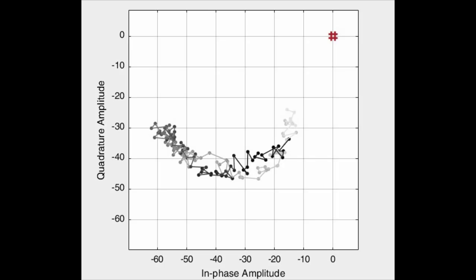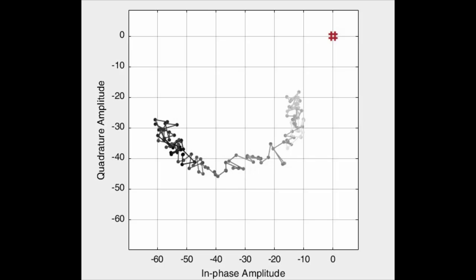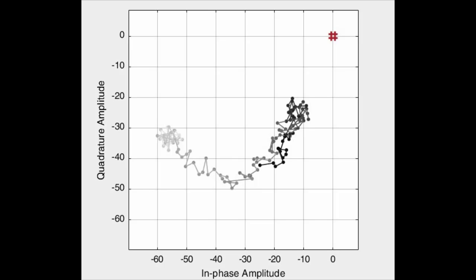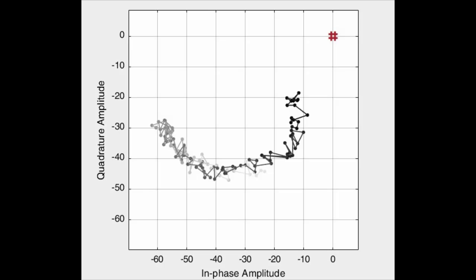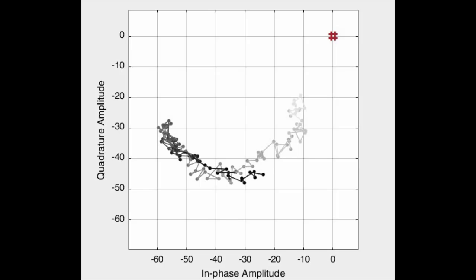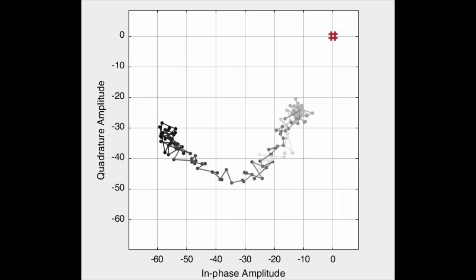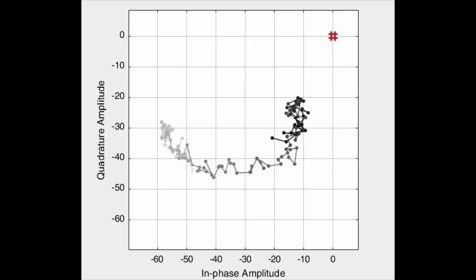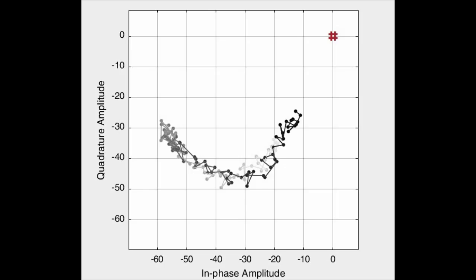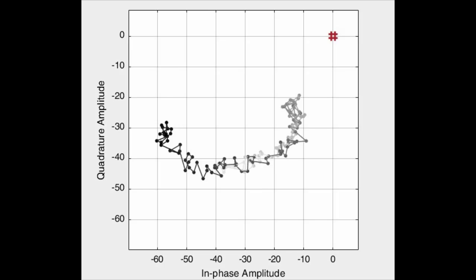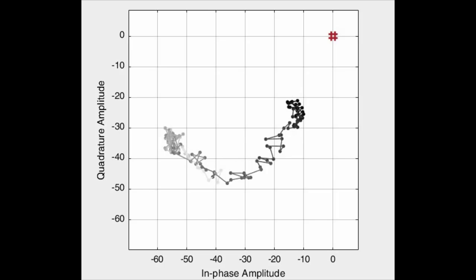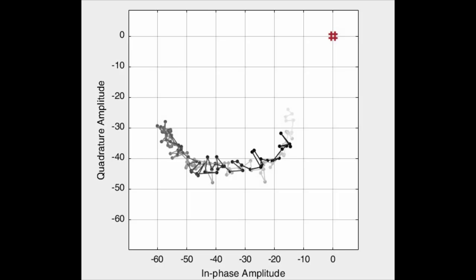The points show us an arc of a circle which has a center shifted from the origin of the plane. That center shift can be shown theoretically when there are two vibrating objects which are modulating the phase non-linearly. The points do not form a straight line; rather, they are scattered around the arc of the circle because of the phase noise we have added, as well as the AWGN and the IQ imbalance effects.